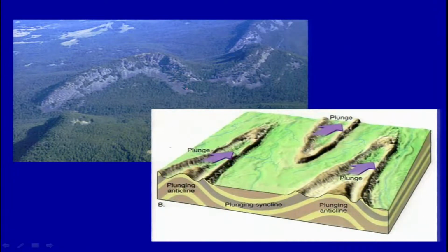Now the point is, yesterday we were talking about what if you select to put a tunnel here. What you will do is extend your tunnel up to this point only, and then you are out, and you don't have to go for a tunnel here. You are getting into the syncline here. So this is one important part that you need to understand, whether this is a complete anticline, or you are looking at plunging folds, or a plunging anticline. This is what will happen.